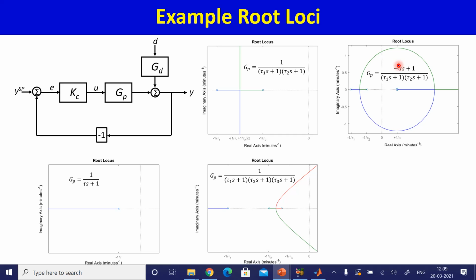Minus 1 by k became plus 1 by k, and so we are looking for those special points in the S plane that cause g to become a positive real number. And so locus is, so now it's clear. As before, you will have asymptotes.